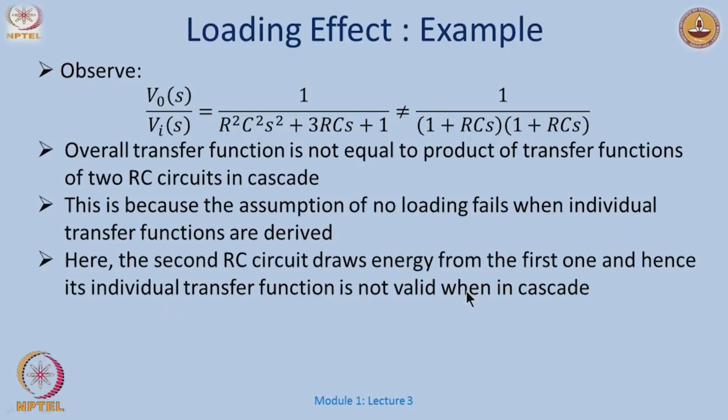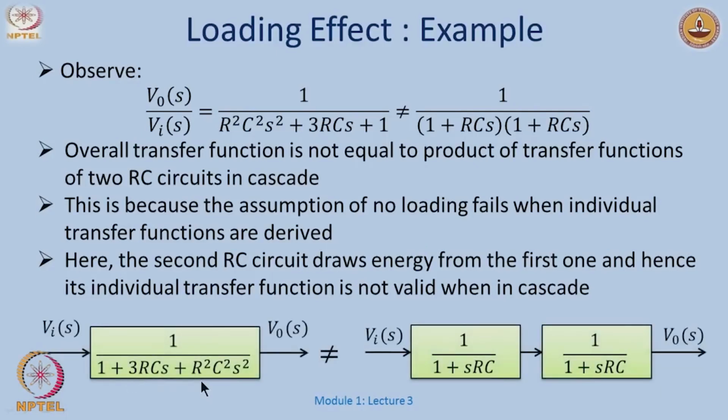is in cascade. So, this is what we have to be careful about when we apply the formula of two transfer functions in cascade, the overall transfer function being the product of them. Okay, we will possibly see a few more examples on this. For the moment, we will just conclude by saying that this is not always true. Of course, there are ways to make this work, which we will postpone to a little later.